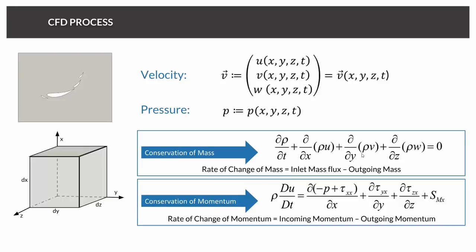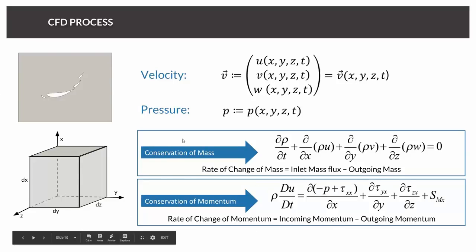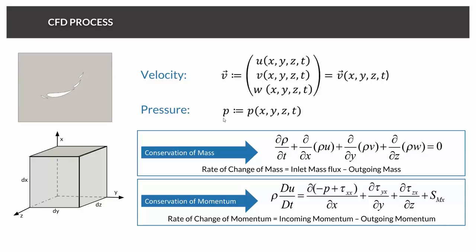The idea behind CFD is very simple. We have these equations which describe the conservation of mass, momentum, and energy. We cannot apply or solve them for complex geometries. So what we do instead is divide our model into small cells or elements. Then we can recompose our complex model from these simple elements, and for the simple elements, we can easily apply the conservation laws.